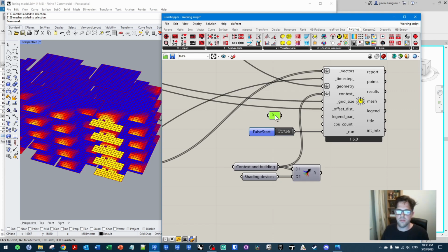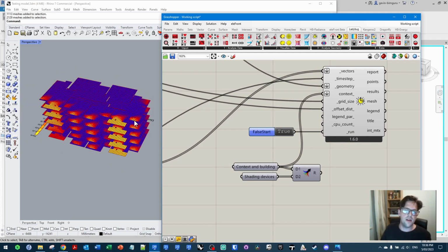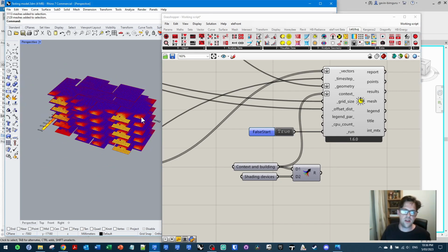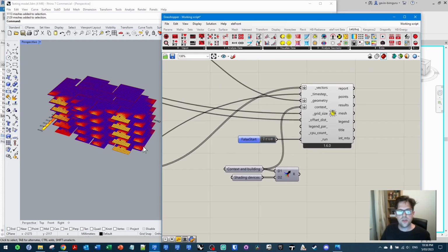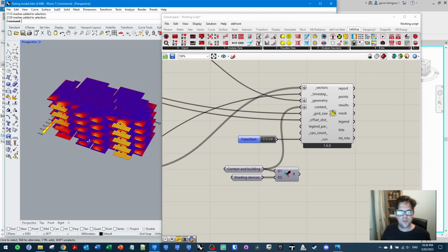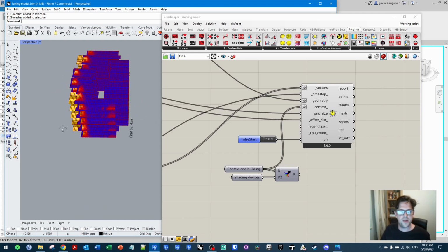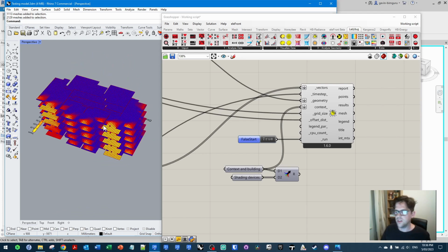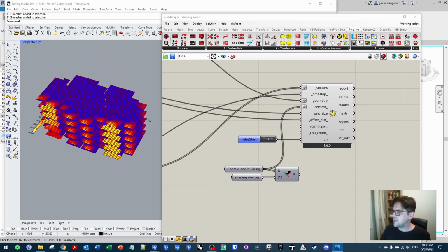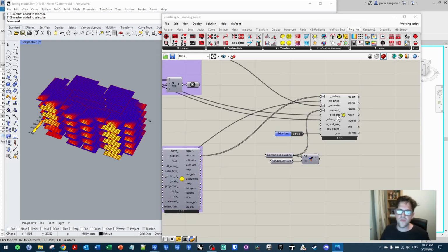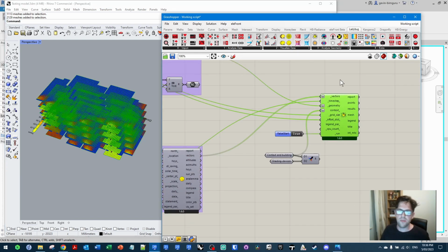So we're working at a meter, and that makes sense because a lot of our windows have a sill height that wouldn't be receiving sunlight that close to the room if not. So we've just visualized the number of sun hours being received by each surface at this particular point. We're going to need to break this down to figure out the sun hours that each apartment receives.